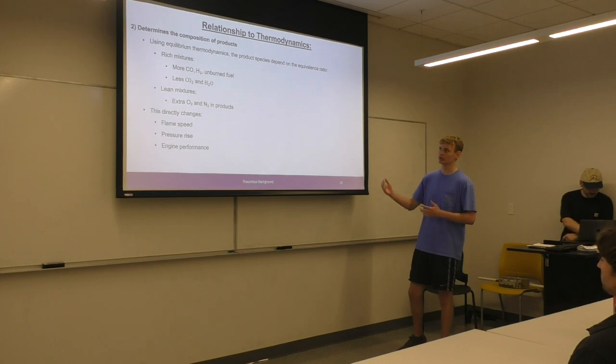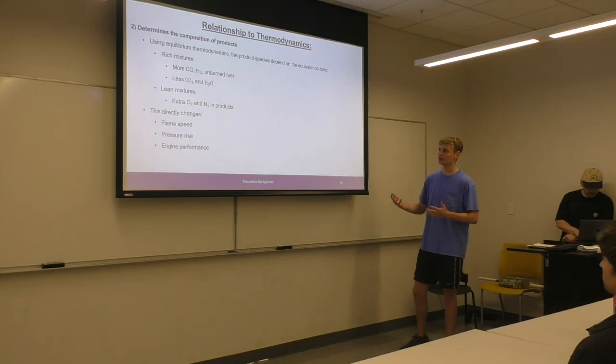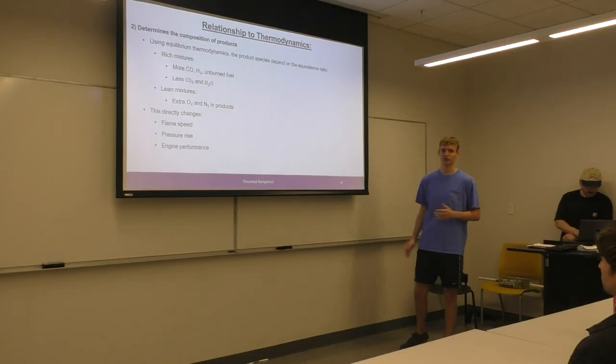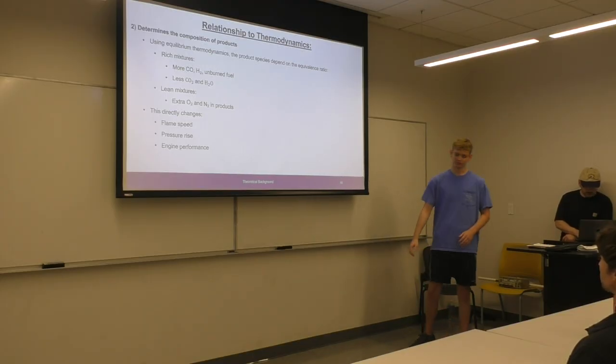But for rich mixtures, you're going to have more CO and H2 and unburned fuel, and then less CO2 and water, which are your ideal products. And then for lean mixtures, you're going to have extra oxygen and nitrogen in the products. And again, I'll have an example at the end that shows a little bit more on this. And this directly changes flame speed, pressure rise, and for IC engines, their performance.